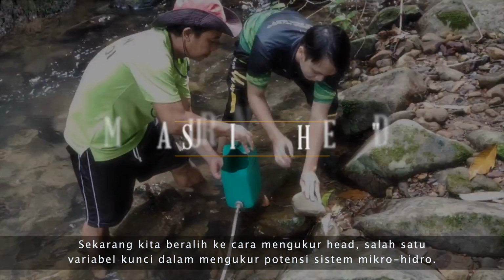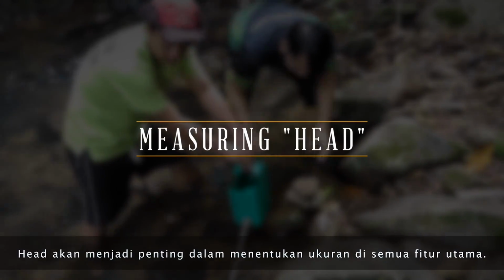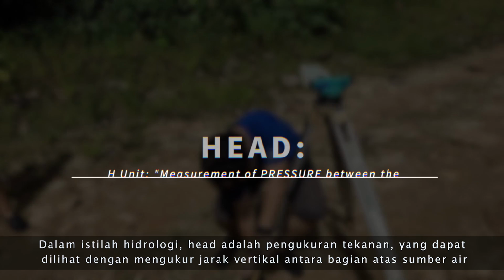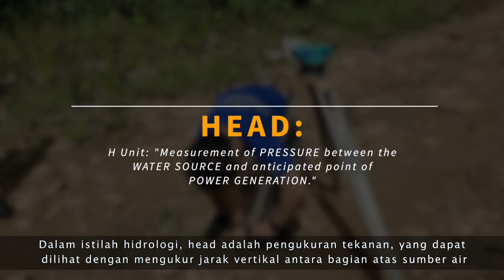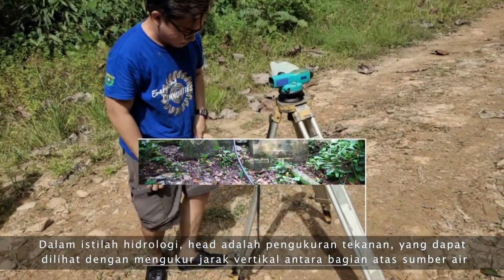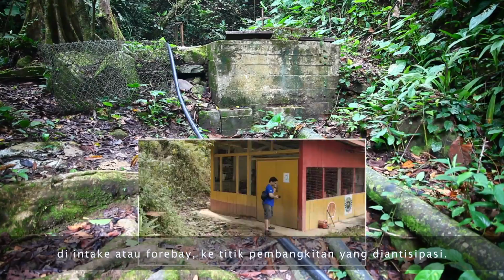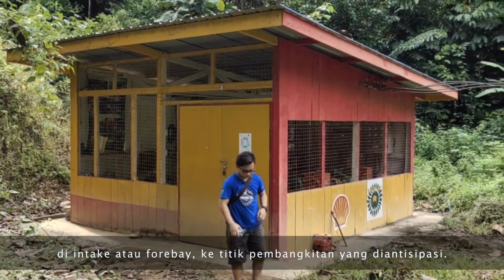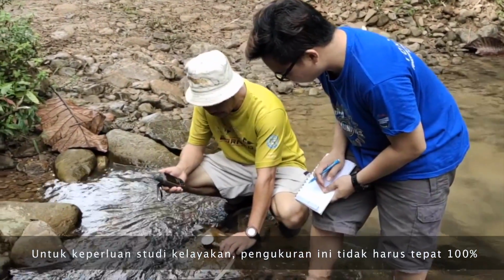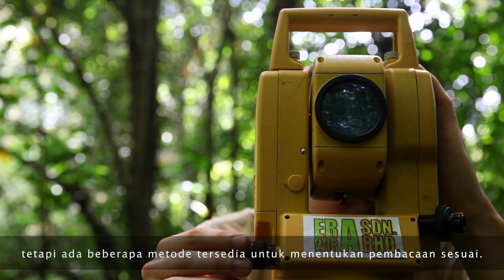Now we move on to measure head, one of the key variables in sizing a microhydro system. Head will be important in determining the size in almost all of the key features. In hydrological terms, head is a measurement of pressure, which can be discerned by measuring the vertical distance between the top of the source of the water, that's in the intake or the forebay, to the anticipated point of generation at the powerhouse. For the purposes of the feasibility study, this measurement does not need to be 100% precise, but there are several methods available to determine an appropriate reading.